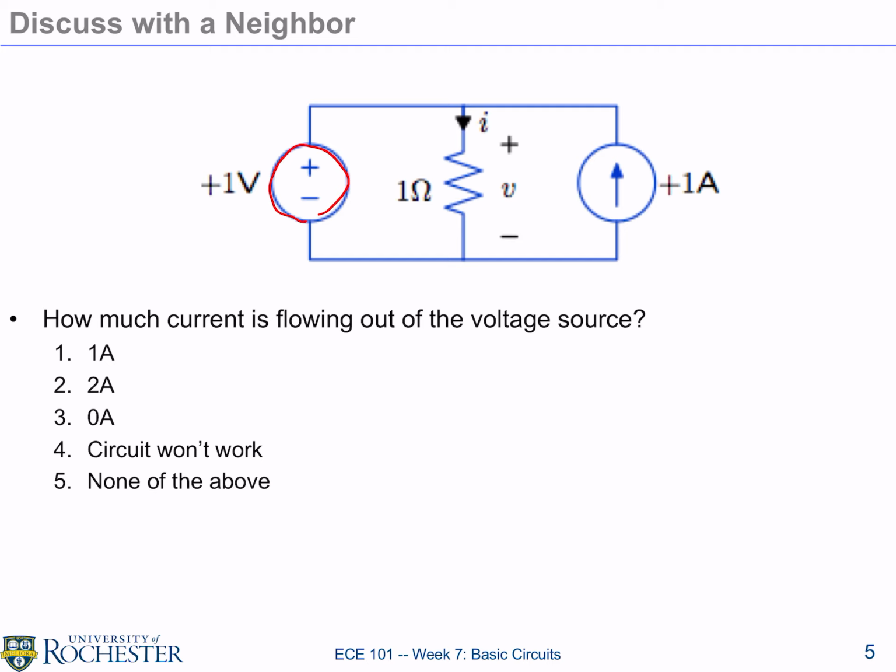Suppose you have a leak, a wire that is not insulated and it was touching ground. Then what you have to do is to change the circuit diagram to reflect what is really happening, and then solve that problem. Then you see what's going to happen, right? So in this case, what are some of the constraints placed? An ideal voltage source places a constraint that says the 2 sides of the voltage source need to have 1 volt of potential difference, 1 volt of voltage.